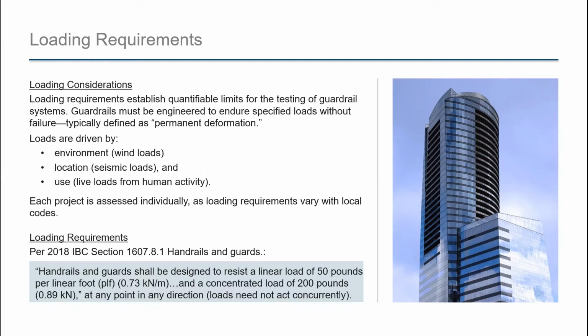Because the location of a building amongst other buildings greatly affects wind loads, many taller buildings in urban areas utilize wind tunnel studies, which use detailed small-scale urban models with pressure measurement devices to determine pressures on specific areas of buildings. This is allowed by code in lieu of calculated wind loads, except in New York City, where the greater of the wind tunnel study and the calculated values must be used. Usually the wind tunnel study does offer you some efficiencies, as the wind loads from the models are usually a little bit lower than those calculated by code.